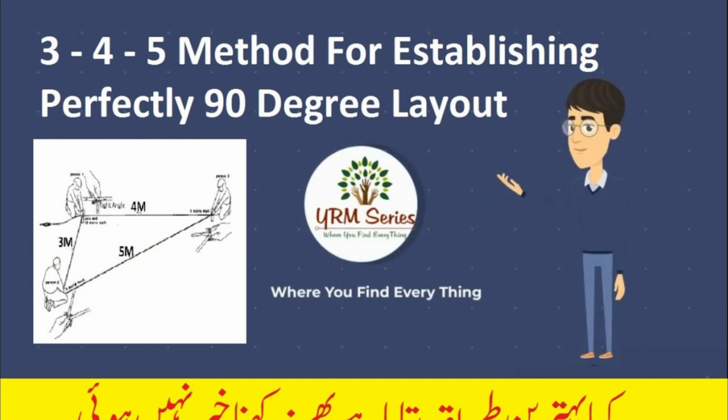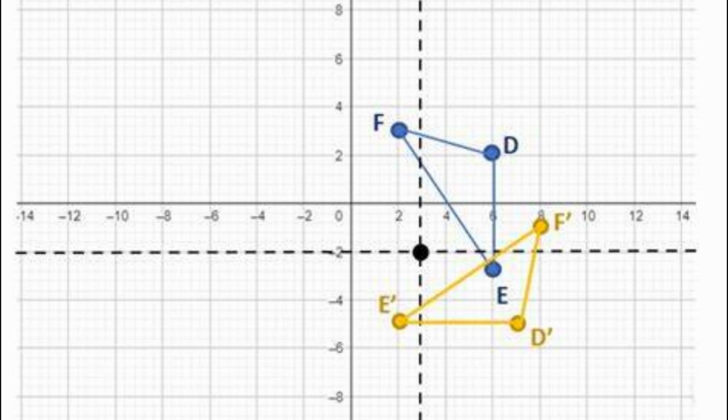By measuring 4 feet from the center to, say, the front, then 3 feet from the same point, you start measuring the 4 feet, but at an angle of 90 degrees. Measure the end of the 4 feet to the tip of the 3 feet, and you should get 5 feet. This method will give a dead 90-degree angle. For smaller rooms, a square can be used.